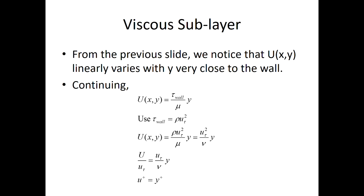We have a molecular viscosity in the denominator. Mu over rho is kinematic viscosity, which is nu. Now you group velocity terms to one side, bring one of the u taus to the other side, so that the left side becomes non-dimensional. It then follows the right-hand side should also be non-dimensional. So now you have a non-dimensional quantity and a non-dimensional quantity. So u normalized by the friction velocity is called u plus.